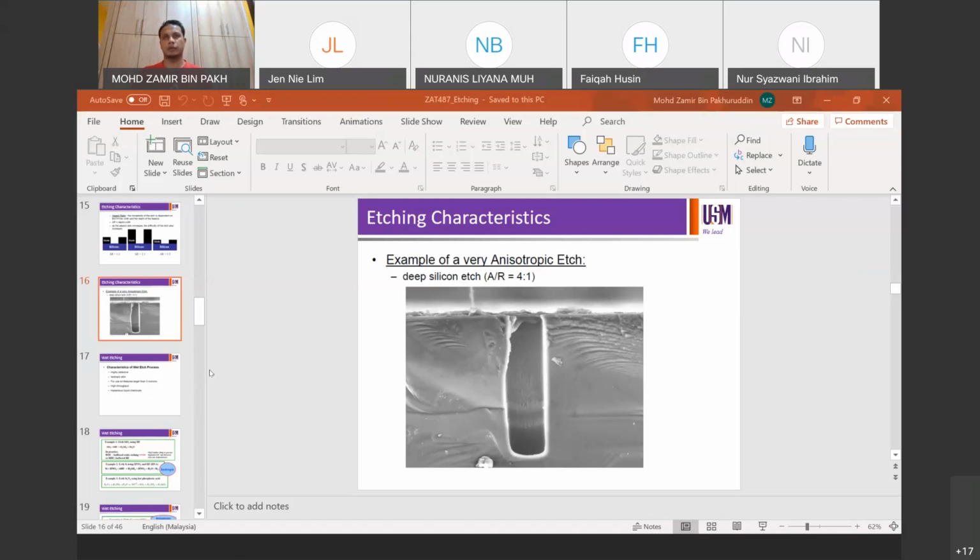To see clearly, you need a scale bar on the cross-section image. In this case there is no scale bar, but judging from the width and size it's somewhere 4:1 or 5:1. To be accurate, you have to use the scale bar on the FIB cross-sectional image.